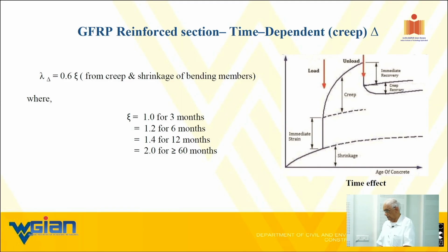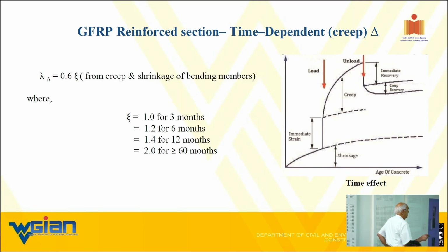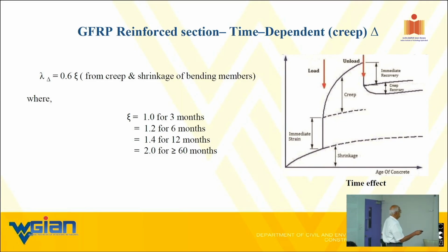Initially, once you remove the shoring, that immediate deflection is primarily due to dead load, but you could have some live load as well, like people walking on it.